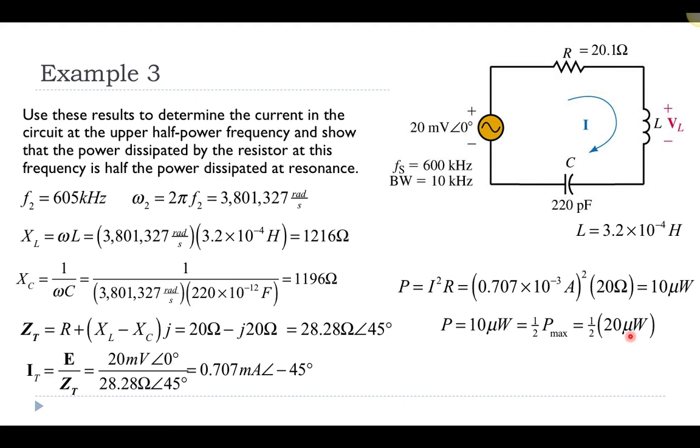Is our bandwidth very small so that we really have to tune things? And we have a lot of power if we have a small bandwidth. Whereas as our bandwidth increases, our power can actually decrease depending on the circuit that we have in terms of its resistance and so on. So these resonant circuits are important when we're building components that need to pick up signals, and that range of signals that we can actually pick up from our circuit.